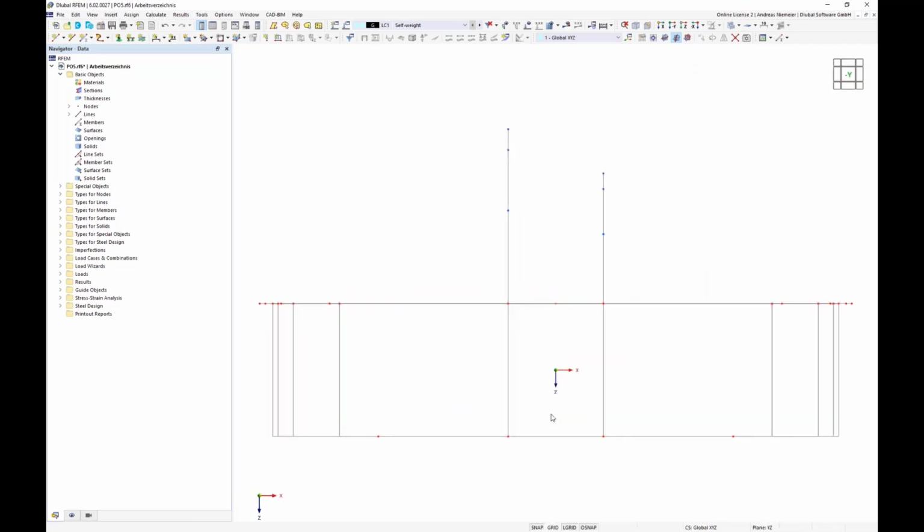Because if we take a look in this view, this architectural concept of this roof forces us to rotate or incline these arcs a little bit, this one to the right side and this one to the left side. Let's assume, for example, 20 degrees. Further, there is a requirement that this top level remains. So when I rotate this arc to the right side, it would go down on the way of a circle or arc. But this level should remain, and the same here.